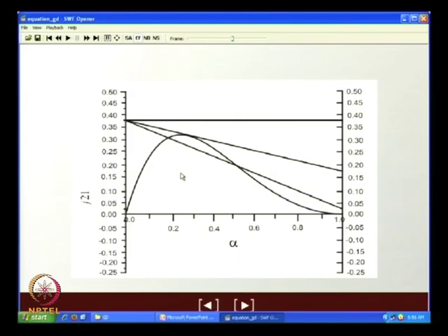So, what do you get under these particular situations? From these situations, we find that below a critical value of alpha, you have 2 points of intersection. That means, for countercurrent flow with gas up, liquid down, there can be two possible flow patterns where the flow can be stable. One is at low alpha.